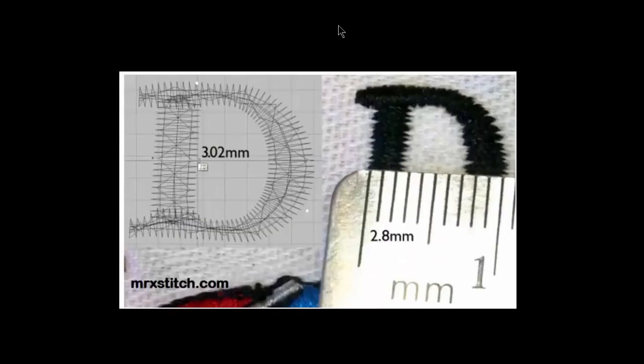If we take a look at this next slide, we see the letter D. If we measure the width of the column of that D, it's 3 millimeters, yet when it stitches out, because of the pull on the stitch direction, we can see that it really is only 2.8 width when it's stitched out. So again, in a TrueType font or fonts that are not digitized, you have to deal with this. In those that are digitized specifically for the software, this happens automatically. It is wider, knowing full well that it will be slightly narrower when it stitches out.